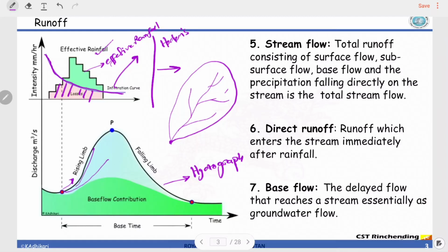It will finally reach a peak, which means that the entire catchment has now contributed its runoff at the outlet, which sometimes we refer to as the mouth. So this point means that from all the remote locations, the rainfall has now reached this point, and then the discharge will gradually decrease, and finally it will reach the normal position, whatever it was there.